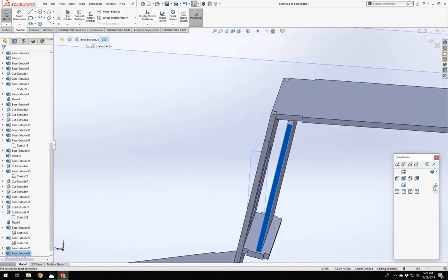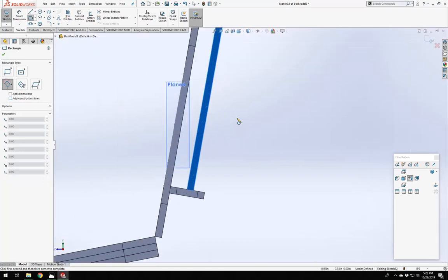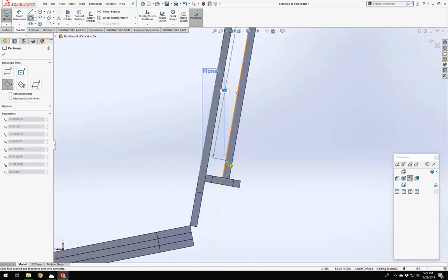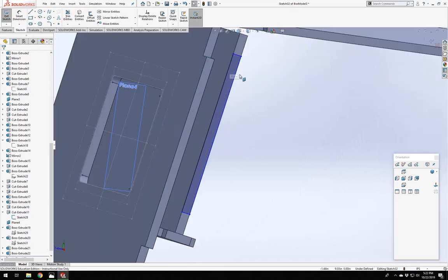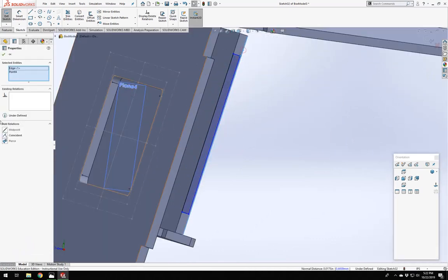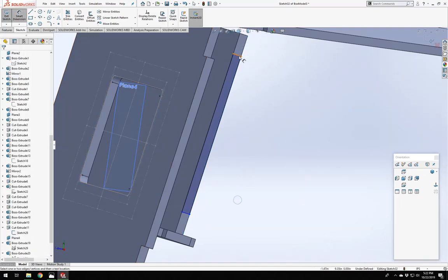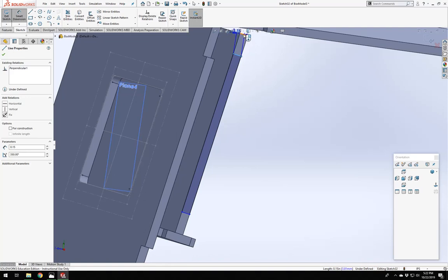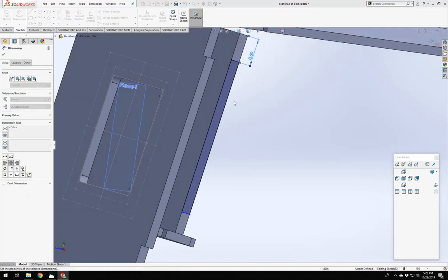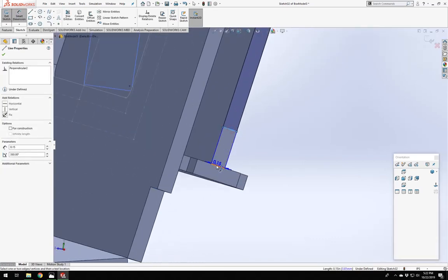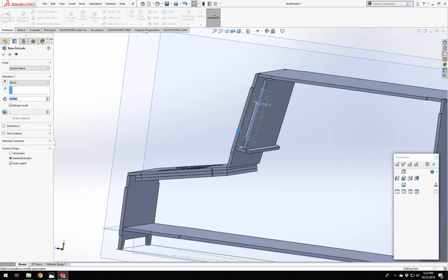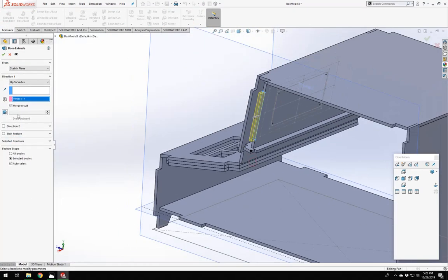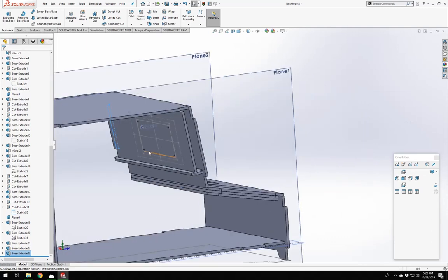Now we're just going to sketch on this side. Again, just making tabs, defining some dimensioning. We can reference that, which is quite nice. Making sure we only merge with itself. There we go. There's one. Let's do the other one.